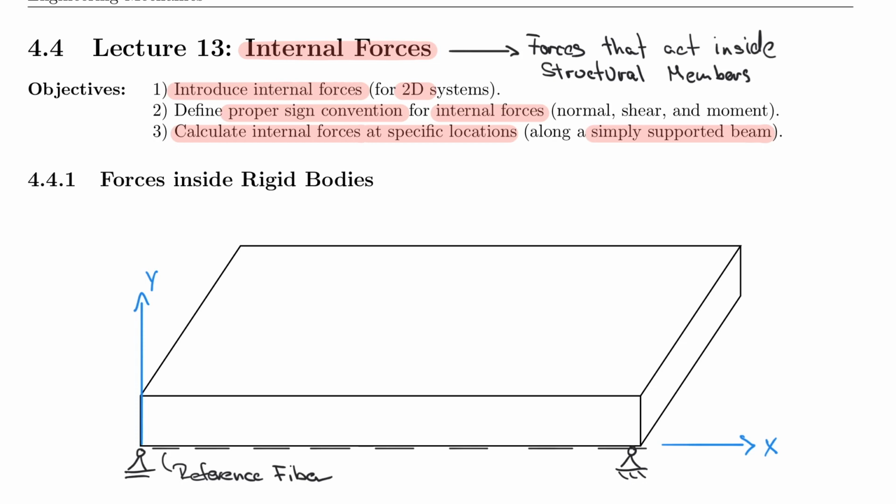So in the context of this table here, I can just cut it, in this case, in 3 individual pieces. And let's just pretend I do it this way. When I separate them, I actually released forces that are inherent to the system when the rigid member is connected. When this rigid member is connected, and you think of this line as the glue line, if you will, then you have internal forces that are connected from one piece to the other.